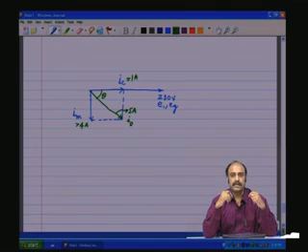Now, all practical transformers will have some flux which does not link the other coils in the core path, and they are called the leakage fluxes. And we will see how we incorporate the leakage flux component into the equivalent circuit model to have a much more complete picture of the transformer. Further, we need to also include the copper loss component into the model.